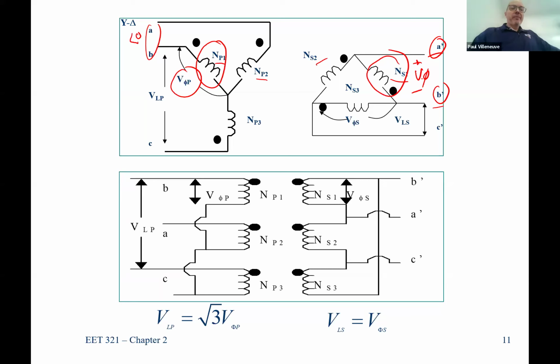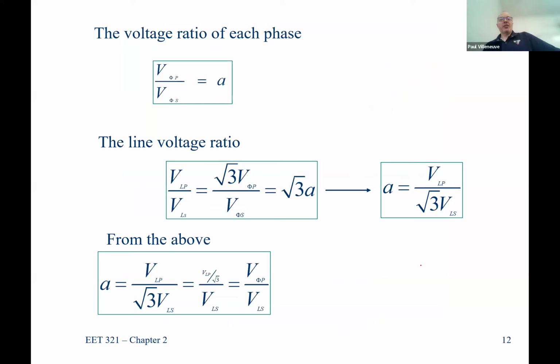But here's how you wire it up. Neutral, and then the delta. Look what I have to do. I have to go through each winding. And if you remember from lab yesterday, I said tip to tail fashion, plus minus, plus minus, plus minus. Aren't I connecting these in a tip to tail fashion? The minus is connected to the plus in all cases. And then I just come out on the individual lines where I have a common connection. That's a delta. And you can connect any set of three transformers in delta Y, Y delta, delta delta, Y Y, et cetera, et cetera.